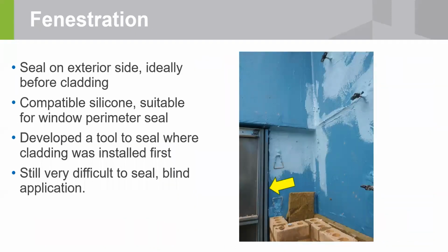Yep. I'm going to this slide because you can actually see that mineral wool material. Hey, not our choice, not our recommendation. That's a different manufacturer, the mineral wool. It's become very popular because of compliance with the fire requirements with NFPA 285. Mineral wool is a non-combustible insulation. So it's not because of thermal or moisture performance, it's because of fire.